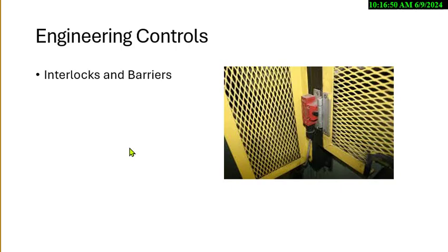But the interlock, we open it up. That's what an interlock looks like. It shuts off. You cannot run the machine while the interlock is disengaged. What you want to do is make sure that when the door shuts, it doesn't just start up again, because you could be in there and you slam the door. So usually there are going to be 3 levels of things that have to happen before it restarts.